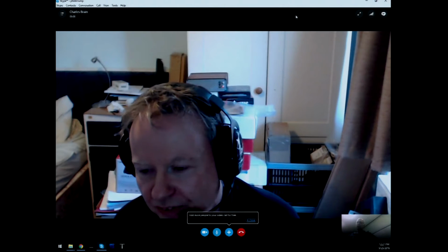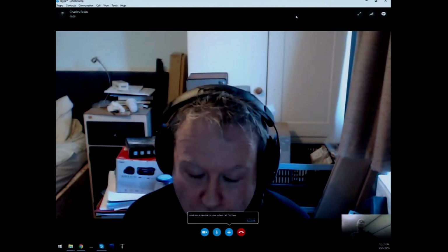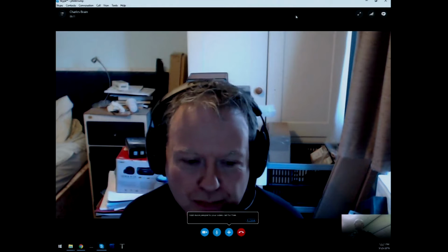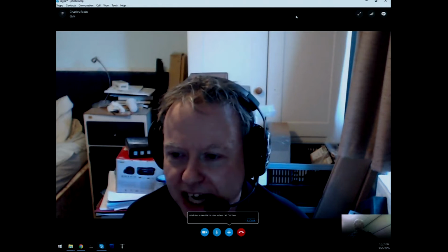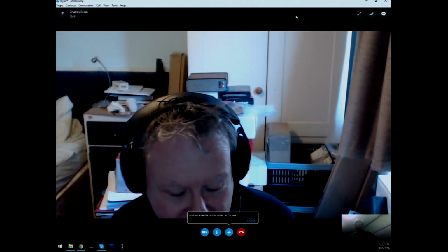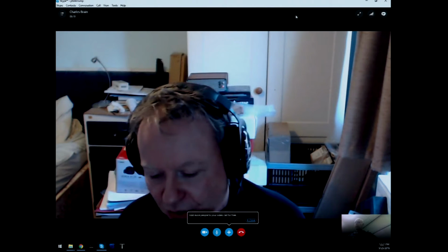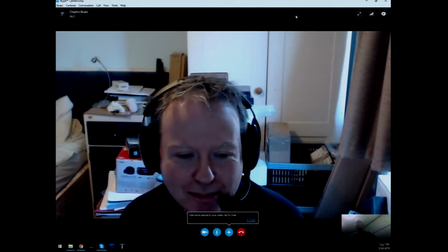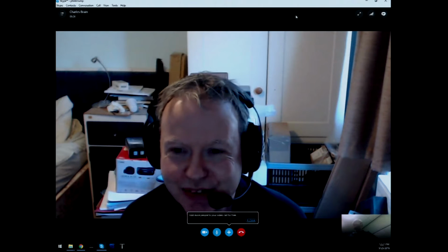It's Jeff, G4GUO. Quick question, DVB-S2 versus DVB-S. Now, given this extra information that's transmitted in the packet, so to speak, does that mean it takes a shorter time to acquire the signal? Well, in theory, yes, it should be able to acquire the signal with a single frame, and a normal frame is 64,800 bits long. So you can work out how long that takes to transmit. In practice, with my SAT scan or SAT-link receiver, it doesn't make a blind bit of difference. It's just as fast or as slow as DVB-S.